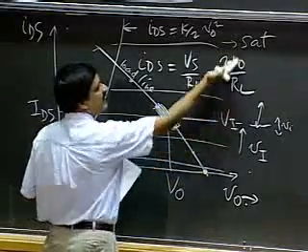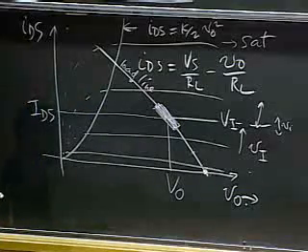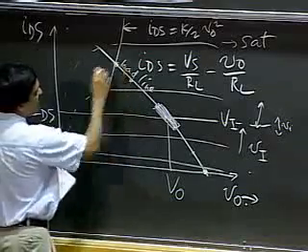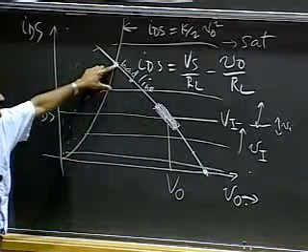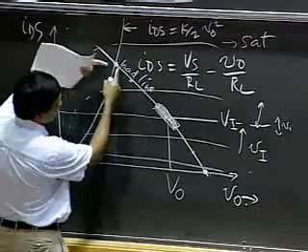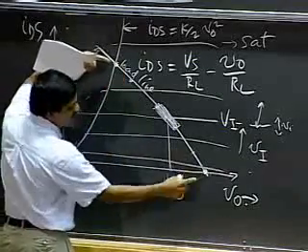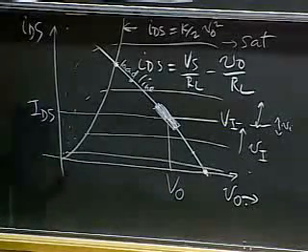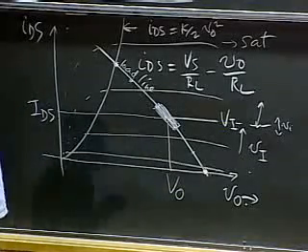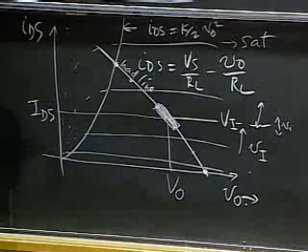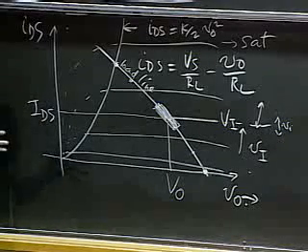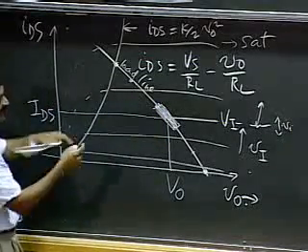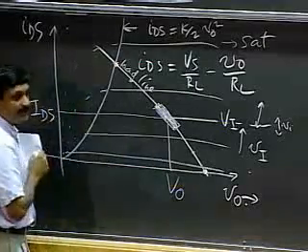Similarly, at the high end, VI could get up to a high value, and we computed that value in the last lecture, and the corresponding value at the input would be here. So I can traverse all the way from here to here and have my MOSFET remain in saturation. Remember, we're not talking about linearity right now, just about the valid operating range based on my definition, which is that the MOSFET should stay in saturation. So if I choose my operating point here, then I get this range here.